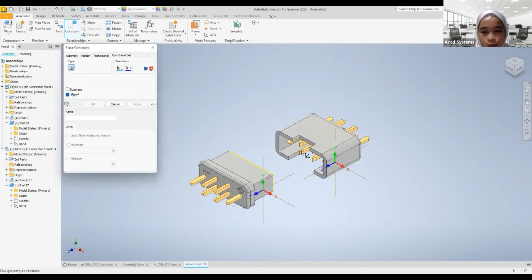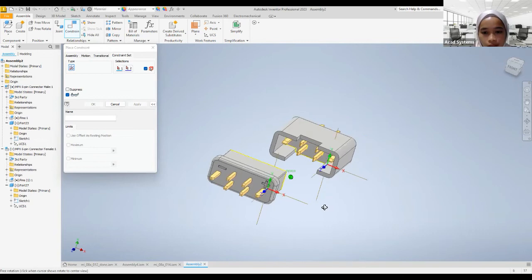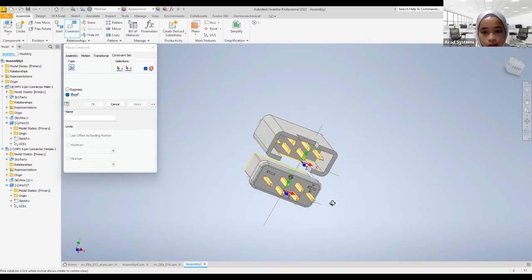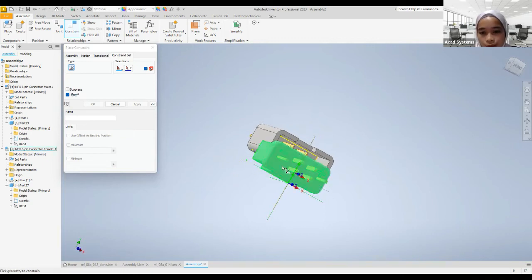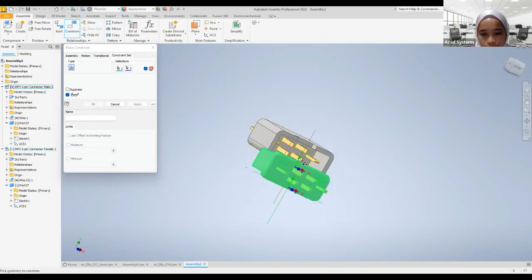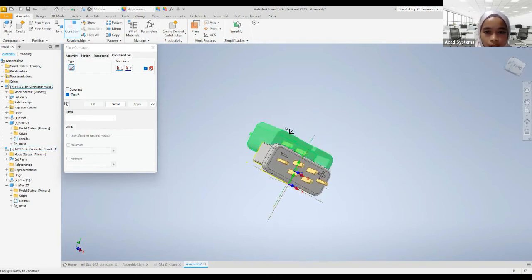Pick Part First is used when you cannot reach the part or the selection that you want to select. For example, like this UCS. Let's say I want to select this UCS. When I activate Pick Part First, it asks me to pick geometry to constrain. I pick this part, and then it asks me to select the UCS.